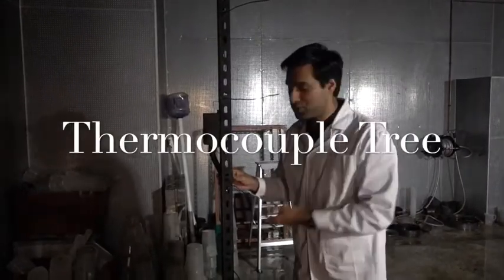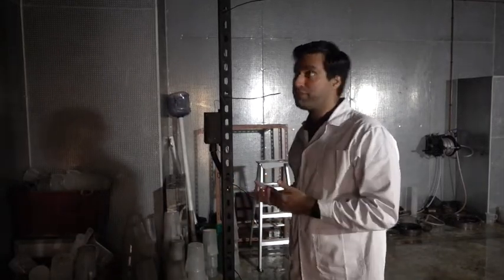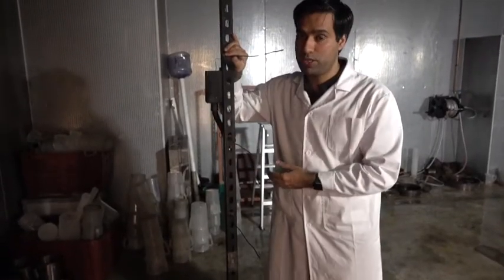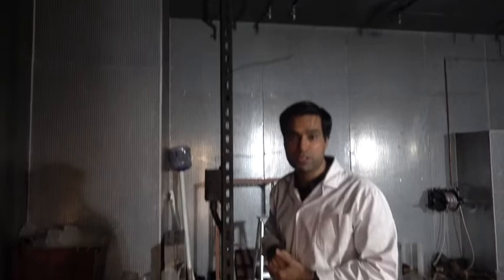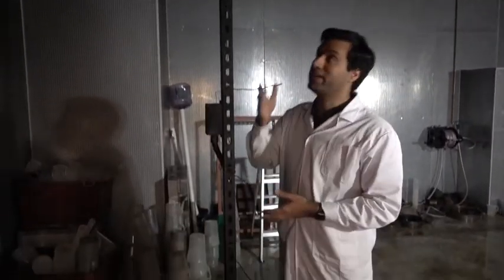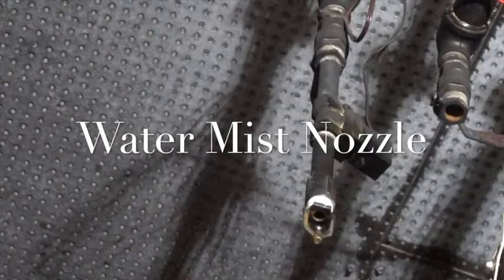This is a thermocouple tree where you will measure the temperature produced during the fire. Each thermocouple is at an equidistance of 30 centimeters up to a height of 2.4 meters, so you can measure the temperature in the vertical direction. This is the water mist nozzle installed on the ceiling, which we will be using for the experiment.